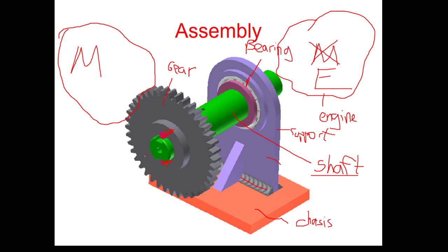Whenever the shaft and the connected other components are going to be under the action of axially directed force or forces, then to be able to prevent displacement in the axial direction, we use such rings. This eggplant color ring, according to its function, is called a retaining ring.